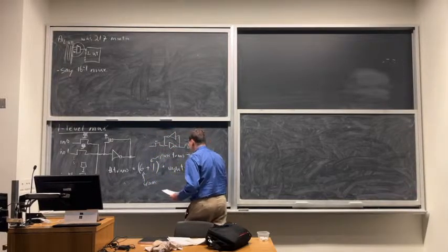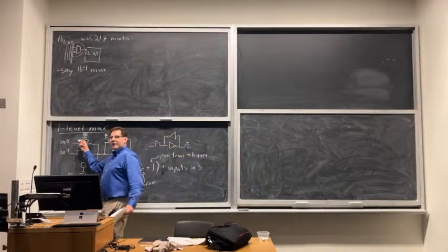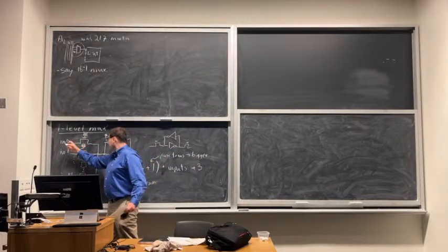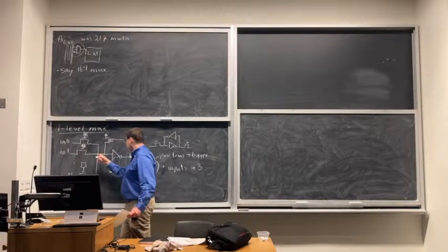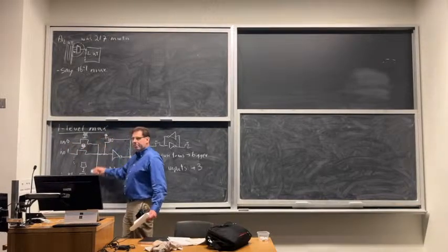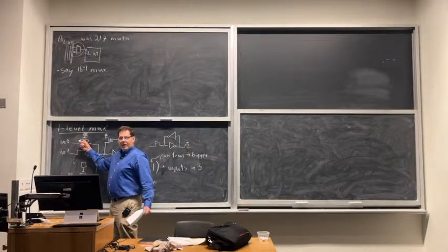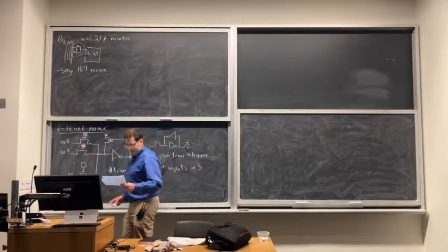Okay, if I want this to be fast, I'm probably going to make this pass transistor, which is on my timing path for the routing, bigger. Getting this signal from here to here, this is a reasonable amount of metal. It's connecting a bunch of transistors. I probably don't want to make this minimum size because it might get slow. So I'm going to assume I make that a bit bigger.